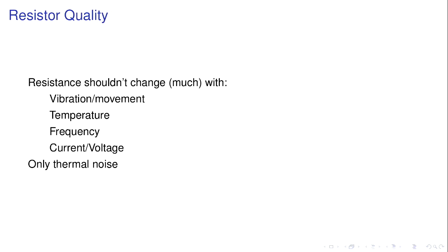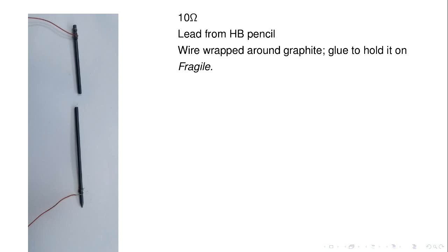I want to produce general purpose ones, so it doesn't matter so much, but you only want the thermal noise. I've had resistors that when you put them in the front end of a circuit, they go noisy because there's something wrong with that resistor. This resistor, I couldn't detect any noise with the instruments I had. But vibration and movement, when I went back the next day, my resistor looked like this. We obviously need something better.